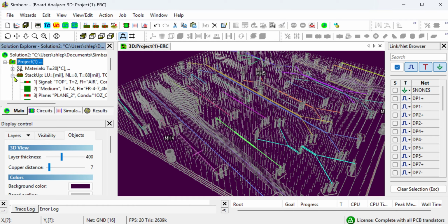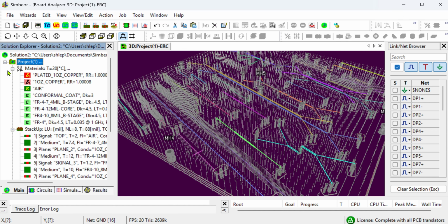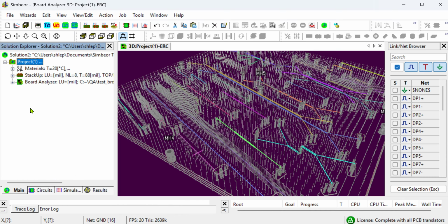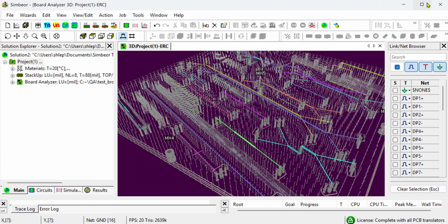It has a simple 8-layer stackup, with some defined materials imported from a BRD file or from ODB++ files. What I want to do is compare it with a PDF document describing the stackup by the manufacturer, how it was going to be manufactured. That's difficult for a human to read, but not so difficult for an LLM.